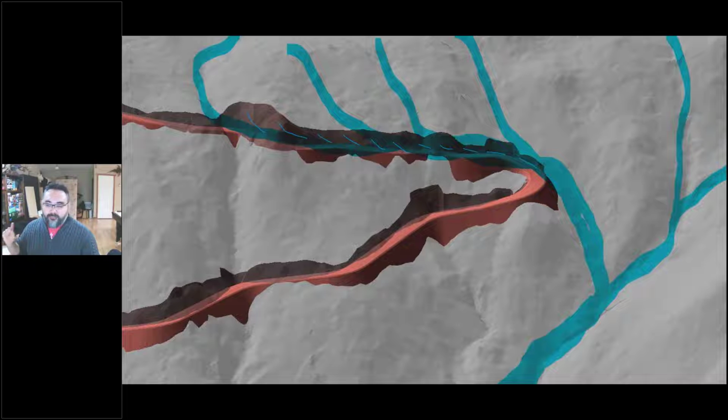So it's important to mention here, I should have said this earlier, that I'm giving you a steep slope example, but this changing of water regimes happens on every landscape, and especially in fine grained soils. Some of our flatter land in Canada and the US, we have a lot of fine grained soils, and just slight changes in soil moisture or cuts into those slopes or gentle gradients can have pretty significant impacts on the stability of those areas.